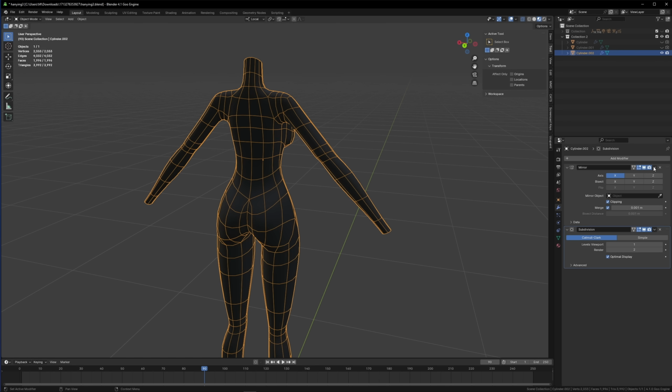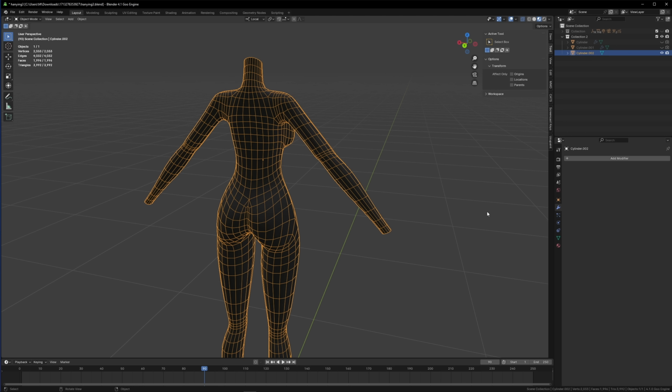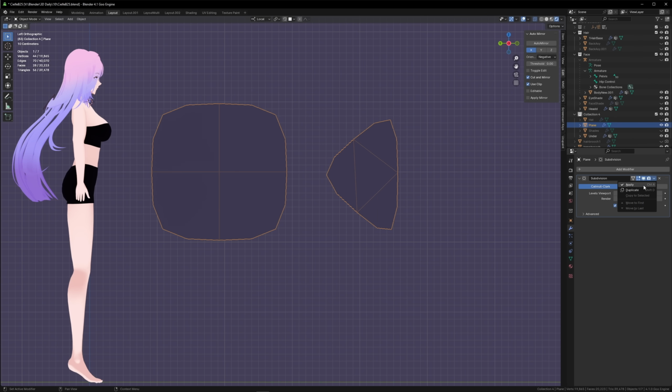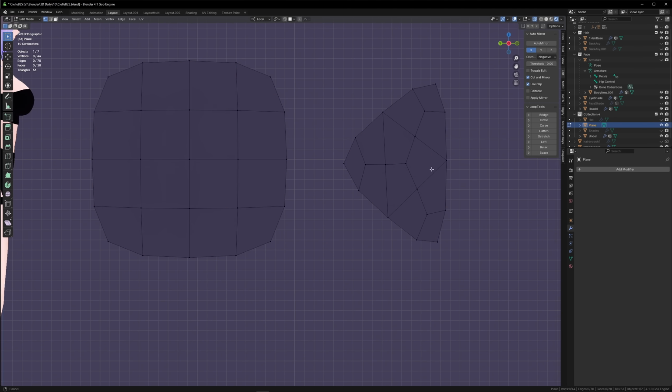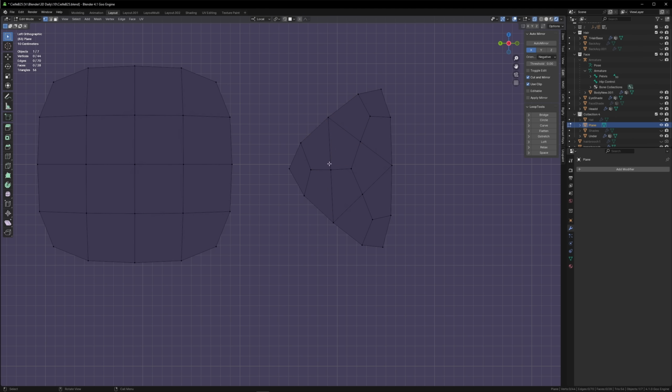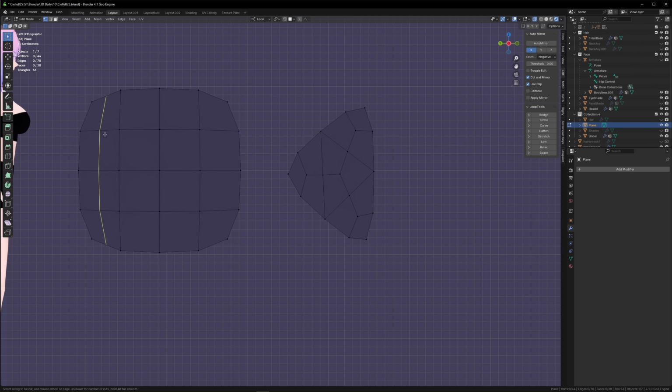When modeling bodies, modelers usually apply a subdivision surface modifier to the body once, giving it a nice curvature and ensuring it has enough faces to work with. When quads get subdivided, they subdivide cleanly into more quads. When tris get subdivided, they also turn into quads, but the result can be a little messy and will definitely need some cleanup after the fact just to make it look more neat. The subdivided quads, of course, still loop cut cleanly, while subdivided tris can also be loop cut because they're quads now. It's just that the routing might be a little unpredictable unless you plan for them, and you specifically use them to route certain parts of the mesh.